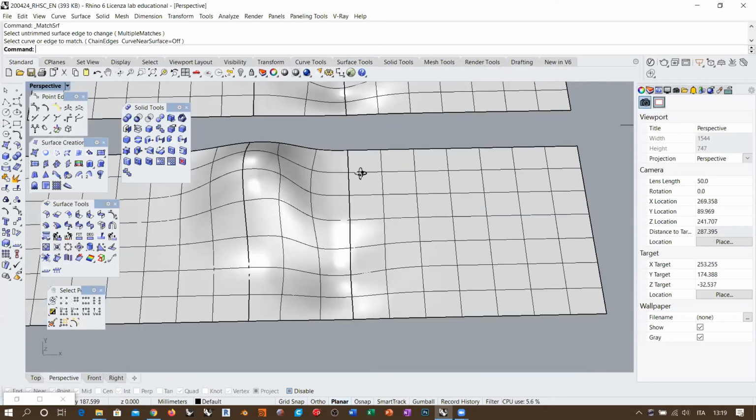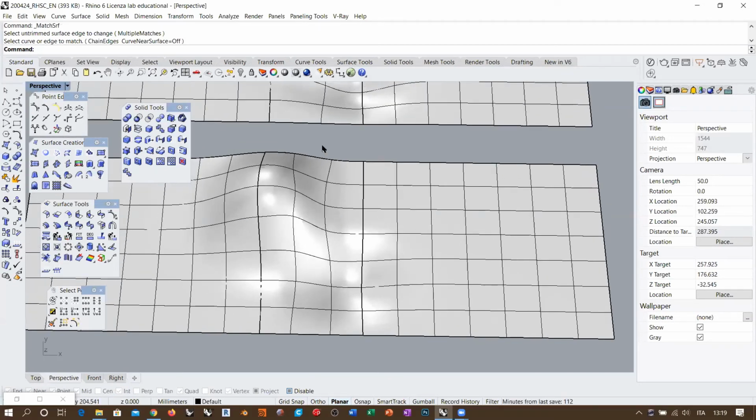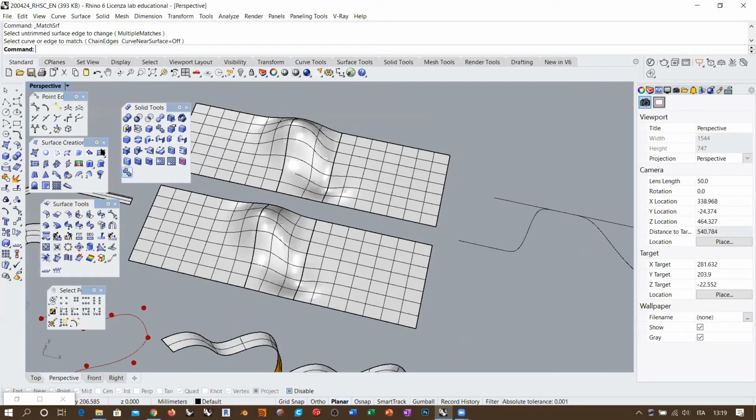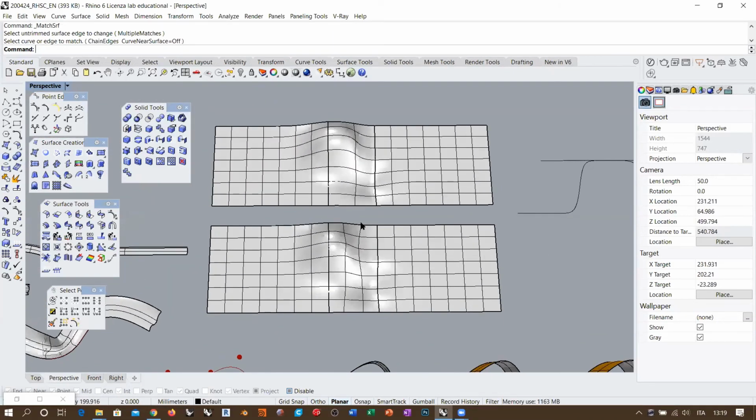So there are operations that depend also on topology and operations that do not depend on topology. There is one particular command that I don't know if we are going to talk about because it's very strange, which is the patch. It works in a totally free way, but suddenly it allows you to adapt to exactly the same topology that you have for, let's say, an underlying surface. Eventually we were going to see this because it's the only way to somehow control the topology of a patch surface. But anyway, it's a very strange command. It's very unlikely that you will use it in your production processes.